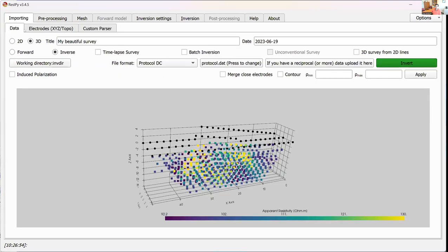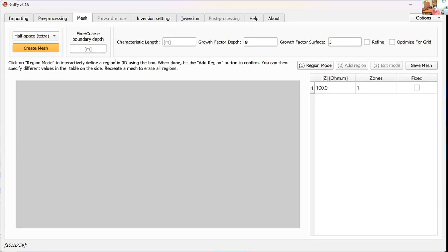This will be problematic if you have really close electrodes, because your non-uniform grid did not really account for spacing, and now there are two electrodes that are really close to each other, and then your characteristic length will become really, really small. Let's say you have a very large survey, and you kind of cross lines over each other, but not perfectly, and your mesh basically becomes impossible to create. Then you either get an error, or you get something like a 2-hour time to create a mesh.